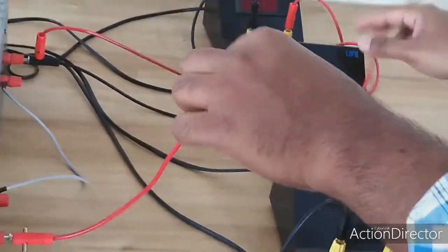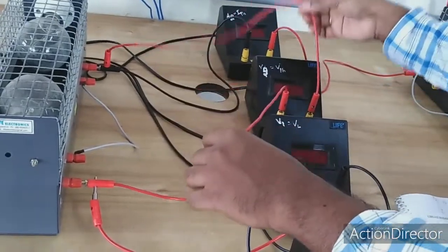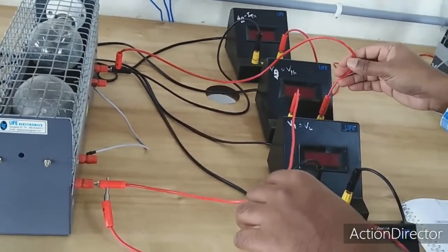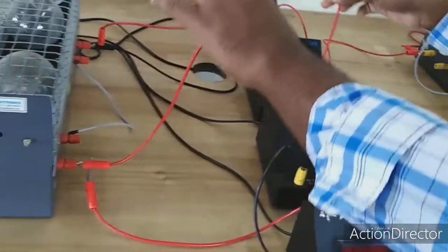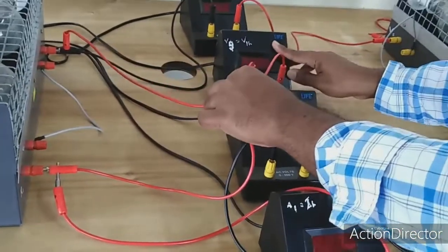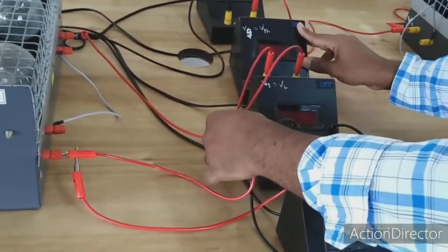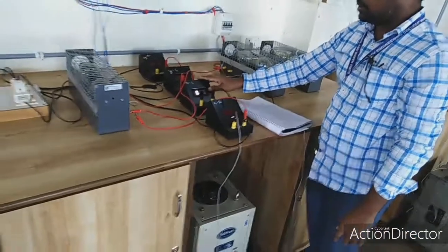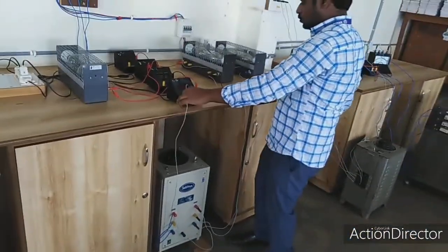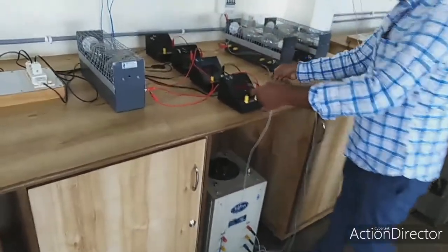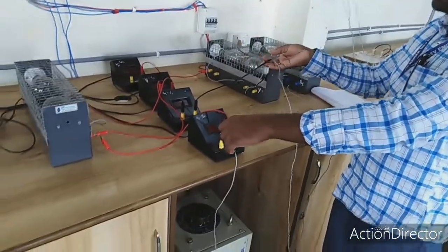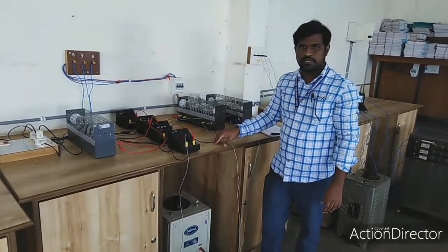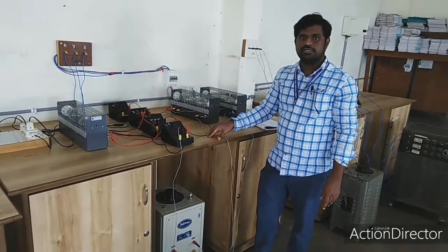So this is R point starting and R point ending. It is connected across the phase winding. So this is a phase. Across the phase I have connected this second voltmeter to measure the phase voltage. So like that we have to connect phase voltage, and line voltage is connected between two lines. This is a line, this is another line. Between the two lines I am connecting to measure the line voltage. Like this, we have to give the connections. Later on we will switch on the supply and we will find the line voltage and line current relations.